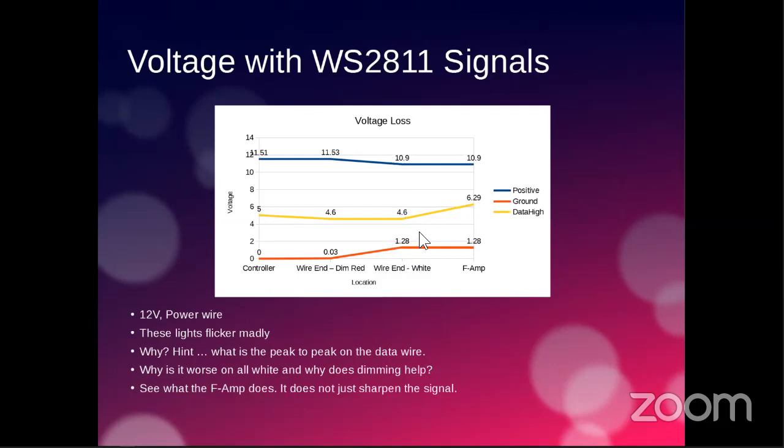But with resistive pixels, the voltage going into the 2811 chip actually varies, because it's proportionate to the input voltage. So once it gets to 10.9, the resistor will drop the voltage to something that's likely under 5 volts, and so you will get less flickering. I'll talk about this in a little while, but resistive pixels are a little bit less susceptible to flickering than regulated pixels are. But once you get past the first pixel, regulated pixels are much better.